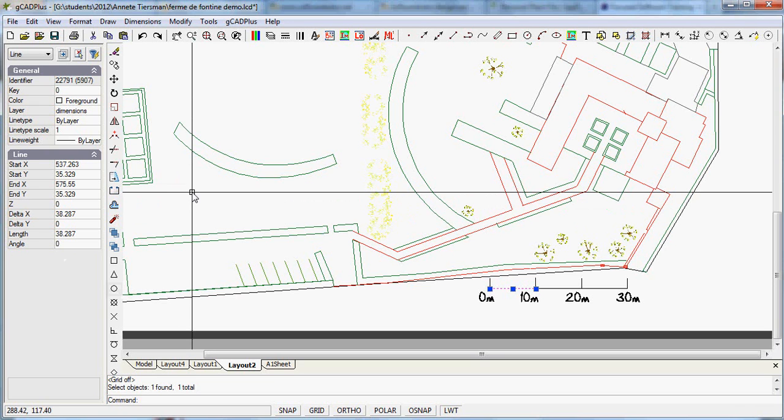And if you make your layout spaces by copying from model space and pasting in here, that creates a great deal of difficulty. What you really want to do is just to set up views, different views of the model in these layout spaces, and not copy. And what I hope to do is to show you the best way to do that.